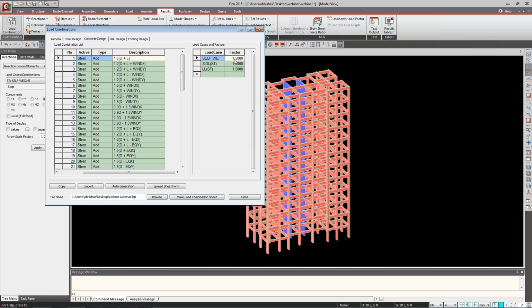Okay, Abhinav Hapse sir is asking one question: what is the limit of the scale factor, or up to what limit can we say the structure is safe? Generally, the limit is maybe below 4. I can say a scale factor below 4, but it depends upon your structure, and the placing of the columns and the shear walls. You also have to go to your drift and cross-check the story drift and deflection.